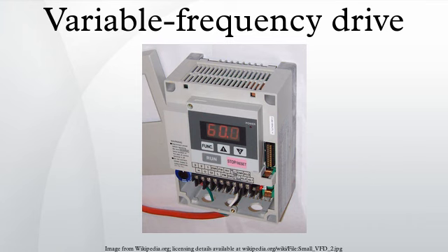Motor bearing currents. PWM drives are inherently associated with high-frequency common mode voltages and currents which may cause trouble with motor bearings. When these high-frequency voltages find a path to earth through a bearing, transfer of metal or electrical discharge machining sparking occurs between the bearing's ball and the bearing's race. Over time, EDM-based sparking causes erosion in the bearing race that can be seen as a fluting pattern.